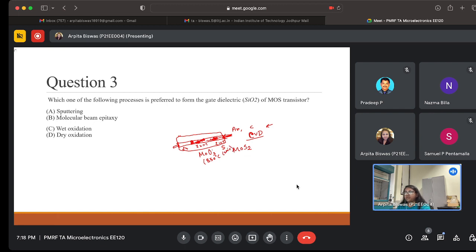We set the parameters so that when zone 2 reaches 850, the first zone reaches 200 degrees, because of the melting temperatures. Then it starts to evaporate, we flow the argon, and it reacts and forms the final MoS2. This is atmospheric pressure chemical vapor deposition.